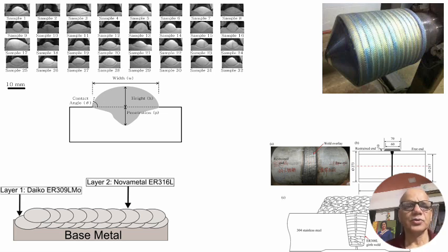So not only welding, while taking NDT also you have to be very, very careful. Post NDT, clean it before you start the subsequent layers. The cleaning has to be as thorough as possible, and wherever you have doubt, grind it, so that only wire brushing or acetone cleaning should not be trusted and believed.